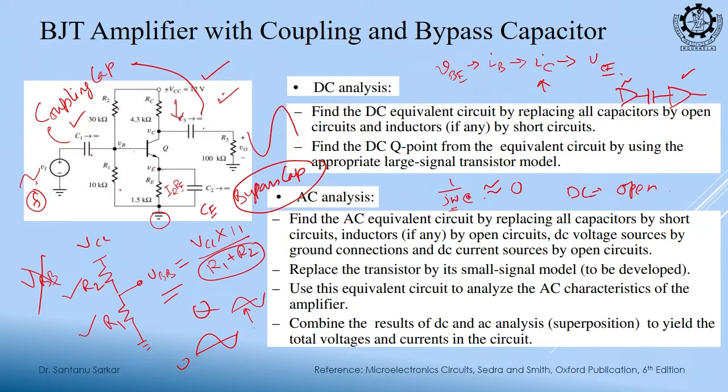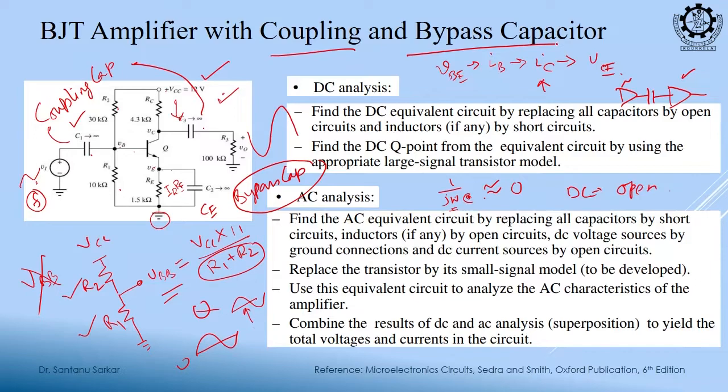So, what it is doing is, as if AC-wise, making the emitter junction shorted to ground. Why, we will discuss this point later, you remember this, why we should do that, I will come and discuss later. So, okay, about the purpose of these two caps: one is the coupling cap, which is used to couple the AC sources and block the DC sources.